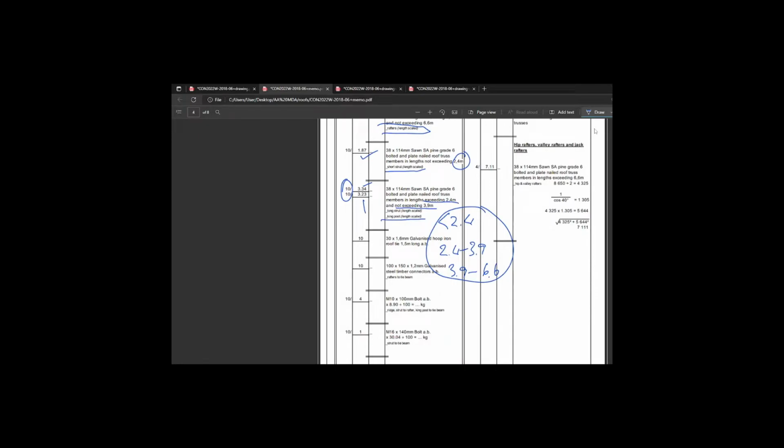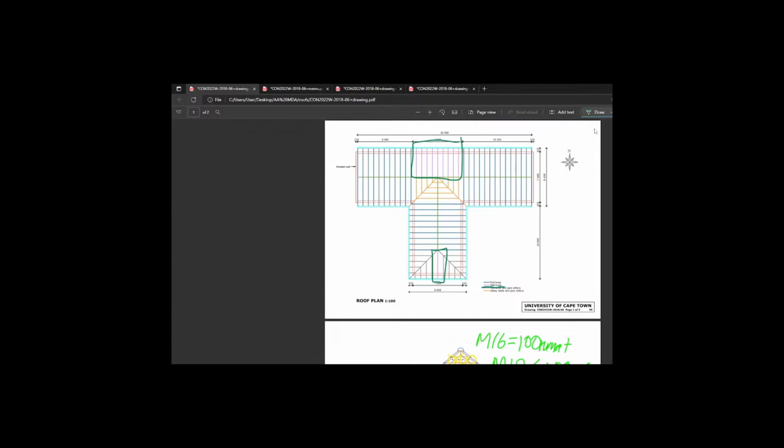Go down. Hoop-iron. This one is interesting and quite logical, which is why I enjoy it. We will take a look. You are putting hoop-iron on a half truss. So a half truss only has bearing on the wall plate once, because it's half. Okay, it's pretty obvious. But if you're going fast in an assessment environment, you could overlook it and just put 2 per half truss. It's 1. Why? The other side is actually bearing down on what we're going to put in later, which is a ridge